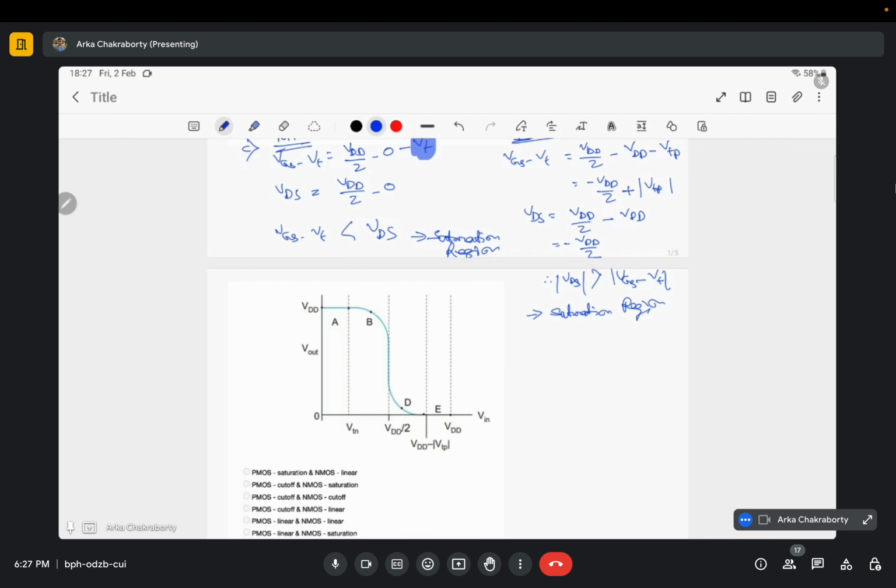See, what is happening here? Let us consider a PMOS. PMOS is a little tricky to handle. There are a lot of conventions to deal with PMOS. The convention that I follow is, I keep the equation same as NMOS, only everything will be negative. VTP will be negative, lambda, CLM, gamma, everything will be negative. There is something called the level 1 SPICE model, where all the parameters are negative. That is what I consider. For your understanding, let me clarify it.